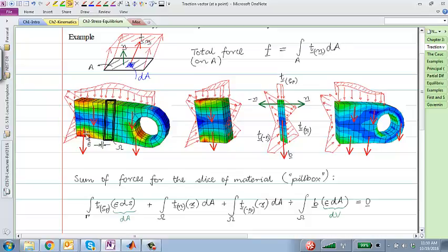Again, I get some reactions, some body forces and everything. In particular, I'll also consider this thin slice of that body. So I have a left side body, a right side body, and a thin slice. If I draw the free body diagrams of these three parts, I would get this free body diagram of the slice and a free body diagram on the right hand side.